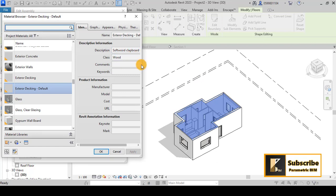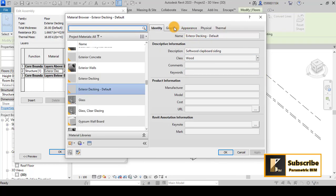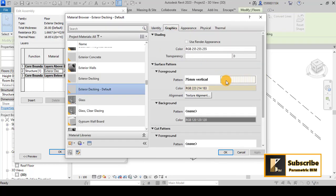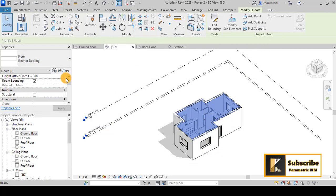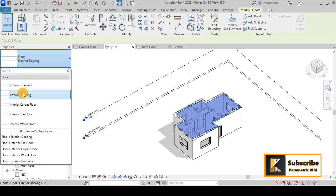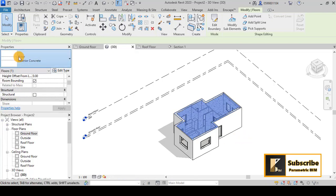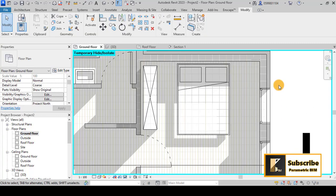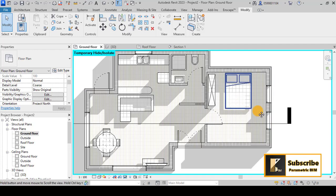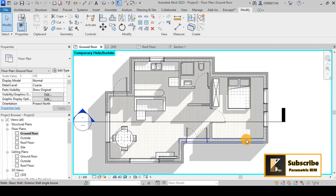If you see that we have exterior decking default, if I come here, you can see from the graphics that we have hatches here. If you want, you can remove it or change this one, only this one, to maybe another floor, let's say concrete, or another floor like that. And I also have these lines, and I don't know why we have them here, maybe because of the view range or something like that, but it is not important.